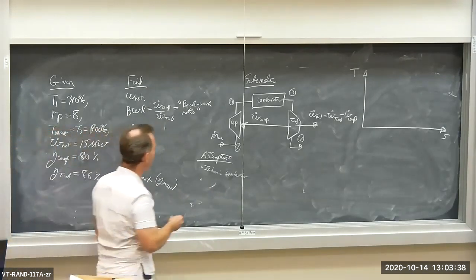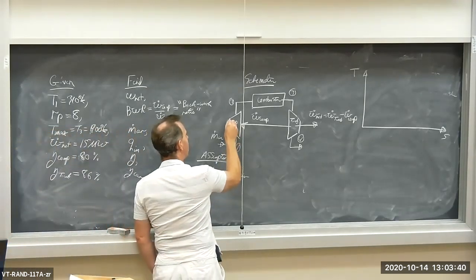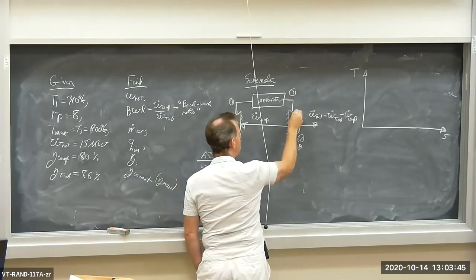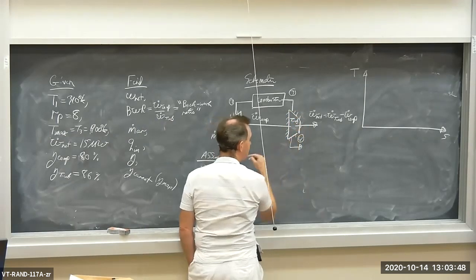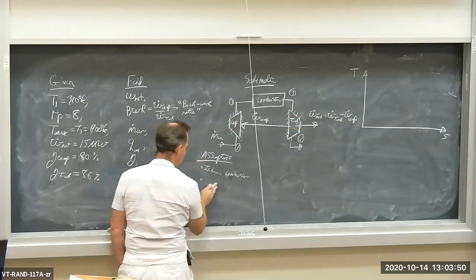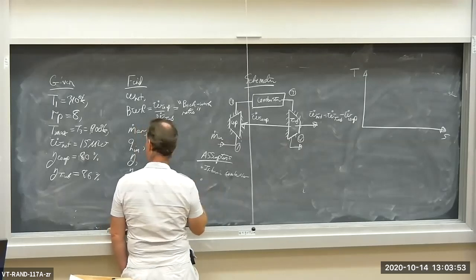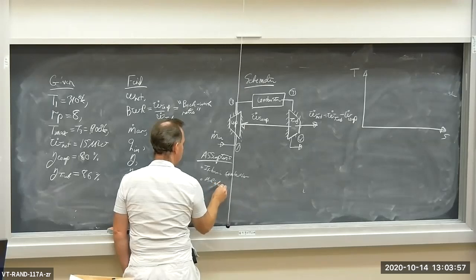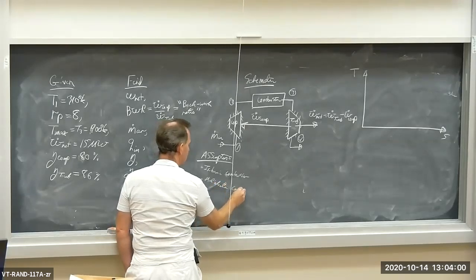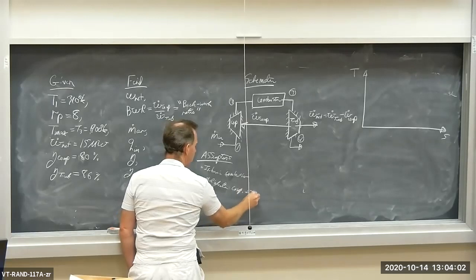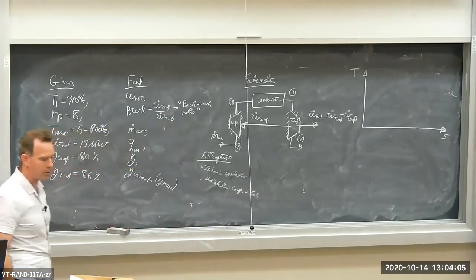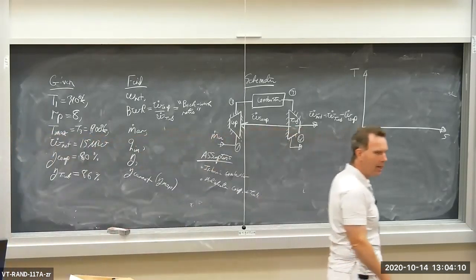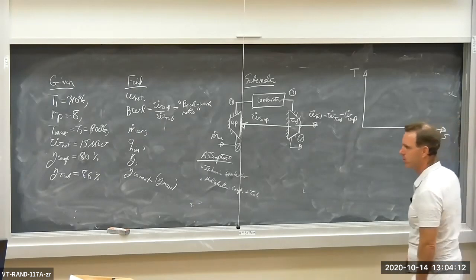I'm going to assume adiabatic compressor and turbine. I don't see anything here, but there's really no way to calculate the heat rejection or addition in the turbine and compressor. I have no information, so I'm going to assume an adiabatic compressor and turbine. We'll move on from there as we need to. Let's draw the TS diagram, therefore, for this process, for this device.